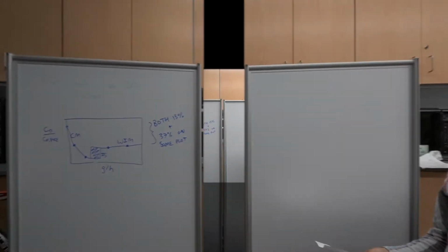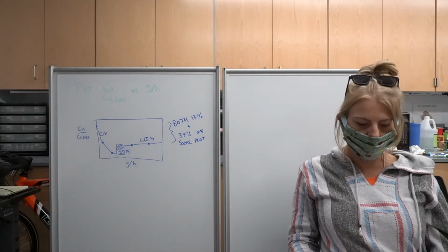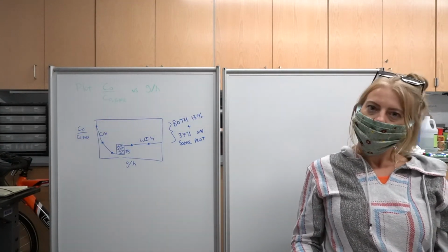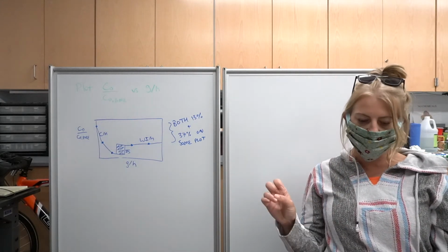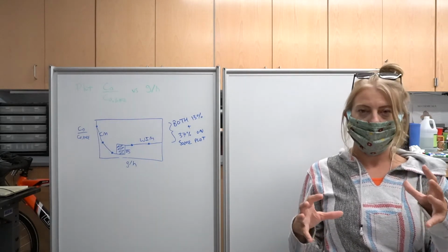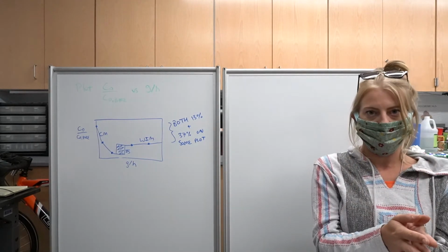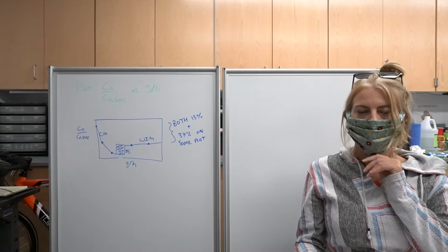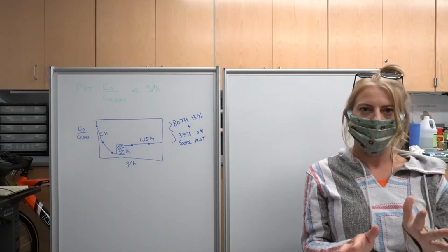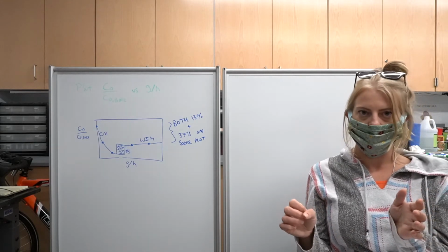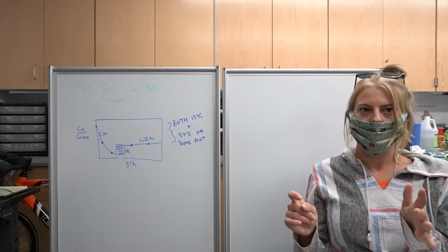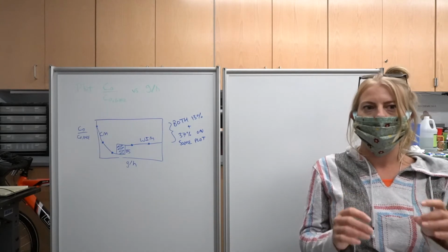So as you're finishing section 3.2, we just want to reiterate that it's important when you are talking about your cavity mode versus wake impingement mode, make sure you talk about the effect on both the front face and the rear face of the cylinder. So it's the decrease of pressure on the front face relative to the bare and the increase in pressure on the rear face relative to the bare that combined lead to that drag reduction.